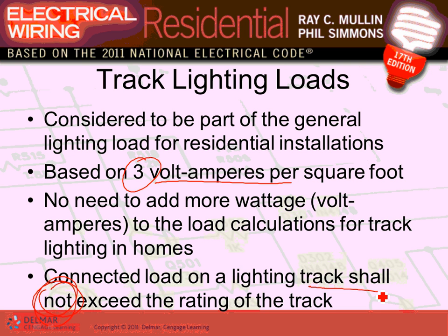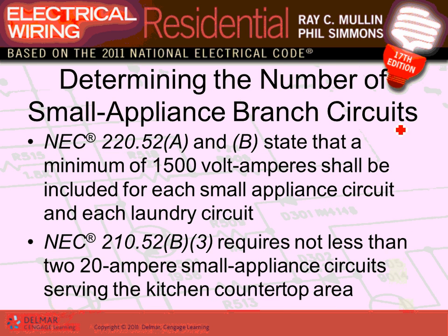Okay, here's track lights. You give 150 volt-amps for every 2 feet of track light. That's allocated load only in commercial and industrial, not in dwellings. Does not count in dwellings. Any comments, guys? Any questions about that? Later, when you have the load calculation sheet I'm going to give you, anything track lights is part of your general lighting for commercial and industrial.